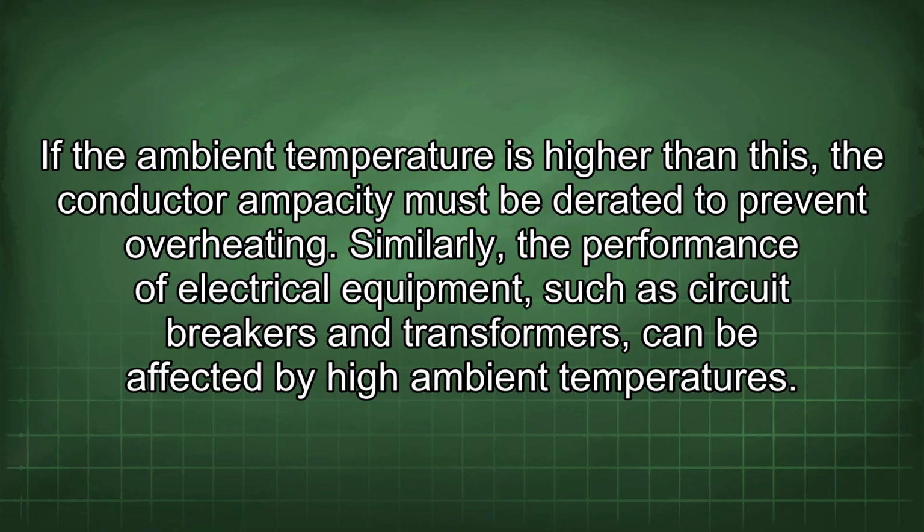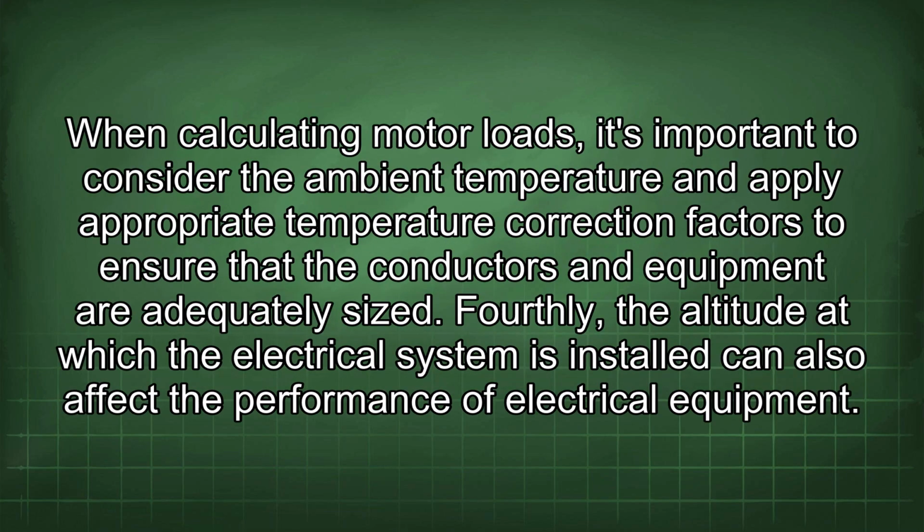Similarly, the performance of electrical equipment, such as circuit breakers and transformers, can be affected by high ambient temperatures. When calculating motor loads, it's important to consider the ambient temperature and apply appropriate temperature correction factors to ensure that the conductors and equipment are adequately sized.